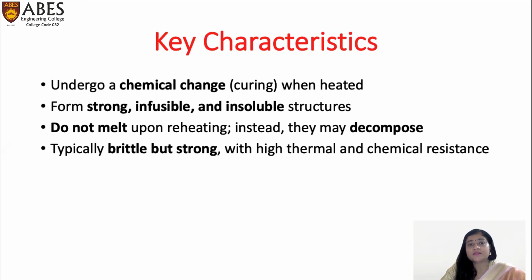The key characteristics of thermosets are they undergo thermal chemical change when heated. They form strong, infusible, and insoluble structures. They do not melt upon reheating. Instead, they may decompose on further heating. Typically, they are brittle but strong with high thermal and chemical resistance.